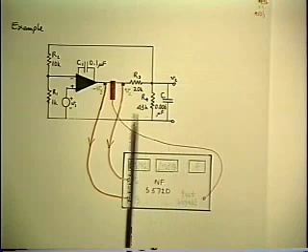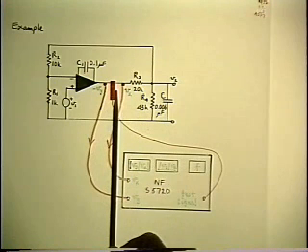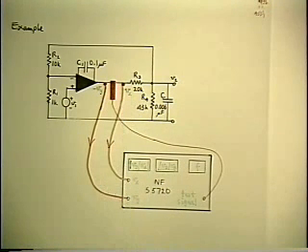Now, again, power supply people don't have any problem with worrying about how you can get a voltage across a piece of wire. Because when you're designing, for example, a 100 amp 5 volt power supply, the secondary winding of the output transformer at the switching frequency is 1 turn, or maybe 2 turns, not of wire, but of copper foil, 1 inch wide.